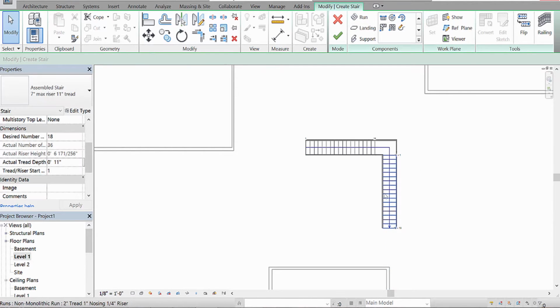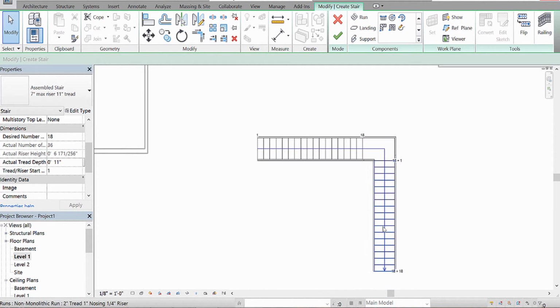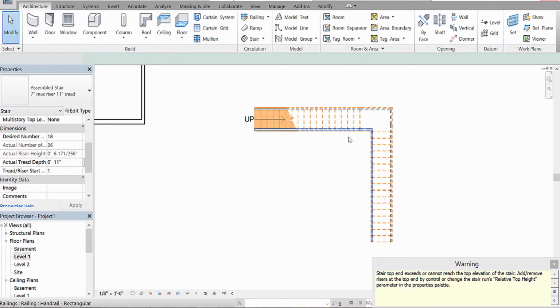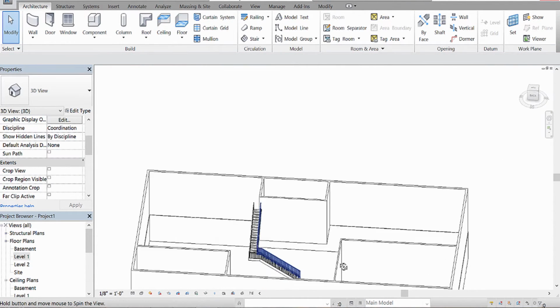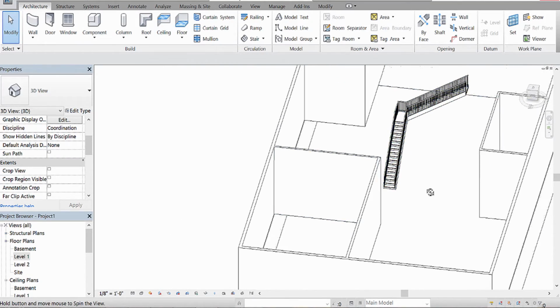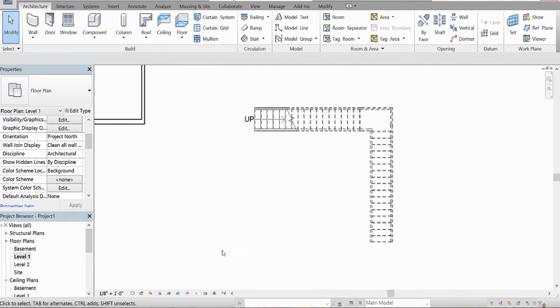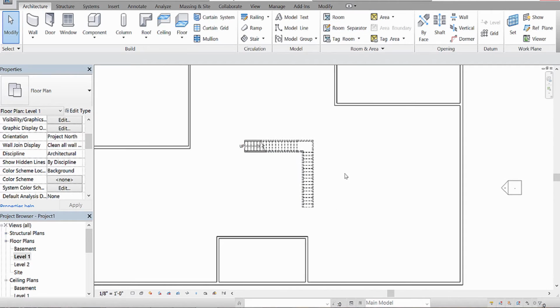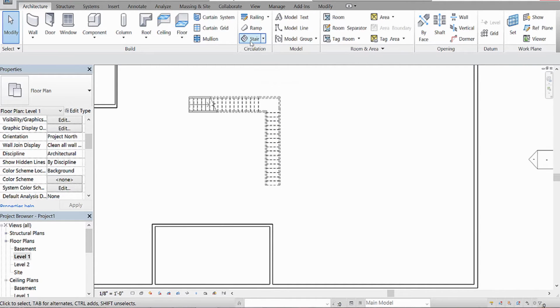and if you notice, you're going to be able to draw in another staircase, and it's going to create a landing for you such that your stairs interlock. So if I finish this, and I head over to the three-dimensional view, you can kind of see what it did there. It simply built my stairs up to the next floor. Okay, every time you need to create a staircase, you also have to go and click that OK button, and then you could create another staircase. Don't create multiple staircases in the same stair option.